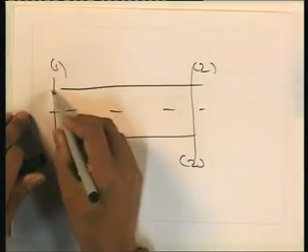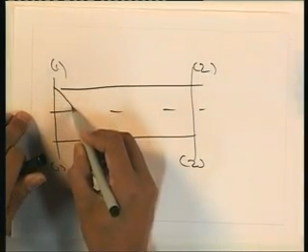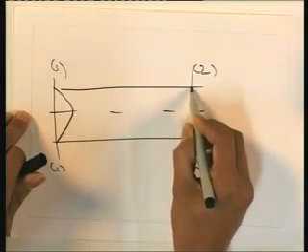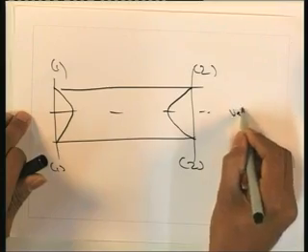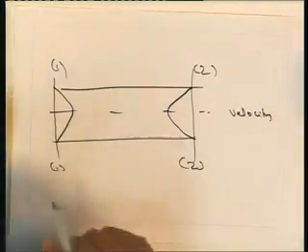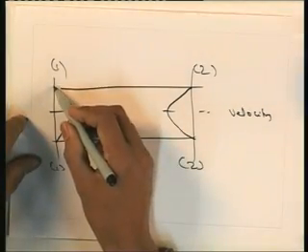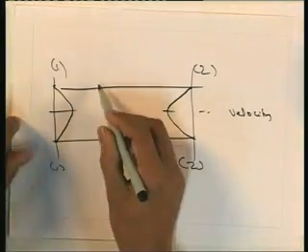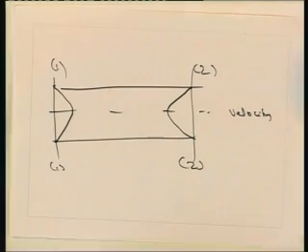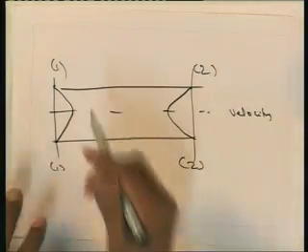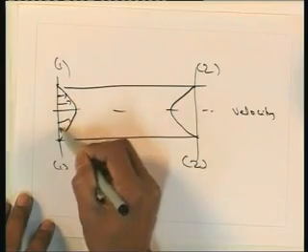If you plot the velocity variation, it will be like this. The velocity will be maximum at the center line of the pipe and it will be 0 at the side wall of the pipe. But the equations which we have derived use the average velocity at a cross section, whereas in reality the actual velocity will be non-uniform and will vary from one section to another.